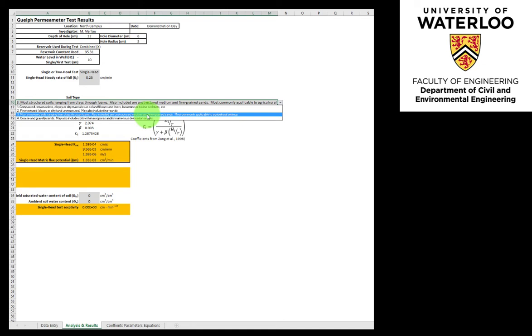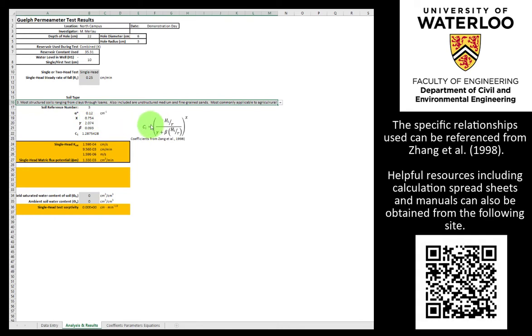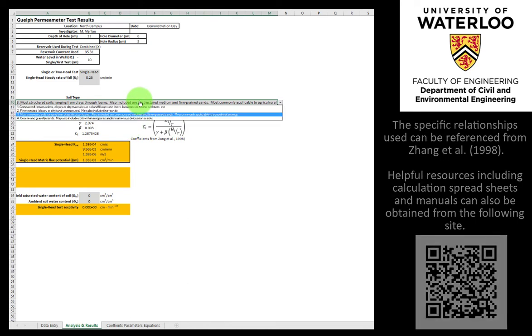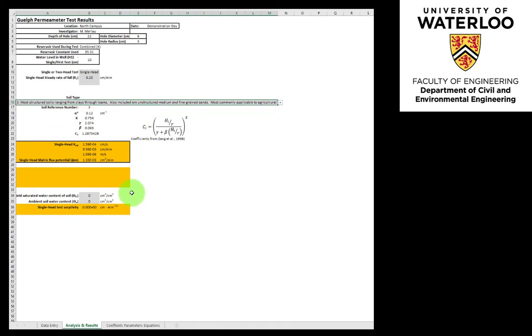For here, we're going to choose the standard number 3 soil type, which identifies various values for the coefficients for our relationship for our constant that's actually used in the calculation of our soil moisture saturated hydraulic conductivity calculations, where X, beta, gamma, and alpha star are going to vary based upon whatever the soil structure is that's selected.